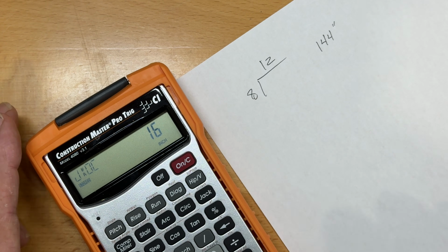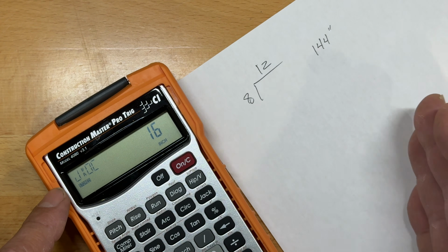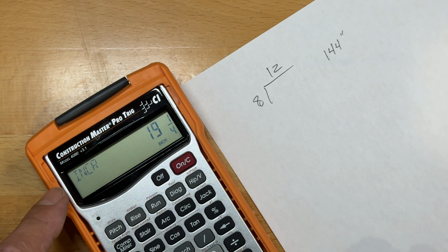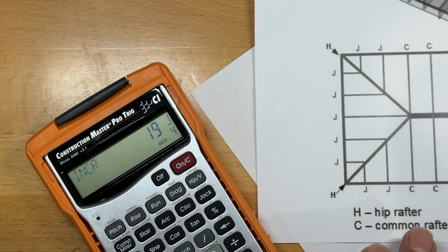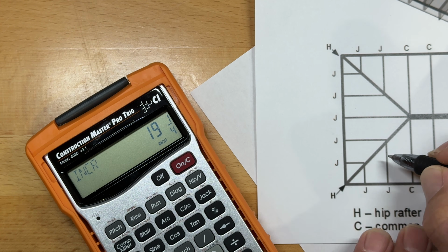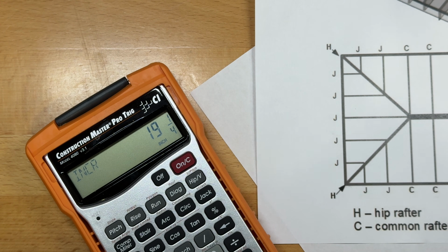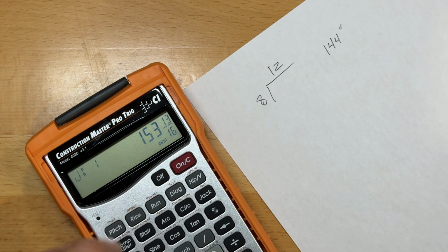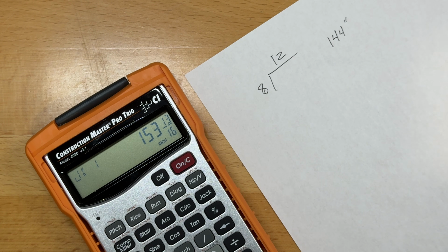Then if we hit the jack rafter, it's going to tell us that our jack rafter spacing is 16-inch on center, and that is correct. Then if we hit jack again, it's going to tell us the increment that the jack rafters are shorter from one another. So the distance from here to here, that length difference is going to be 19¼ inches on our example roof, and that is also correct. Where it is wrong is in the placement of the first jack rafter, which shows the length at 153 and 13/16. This is actually about a ½ inch longer is what it should be.